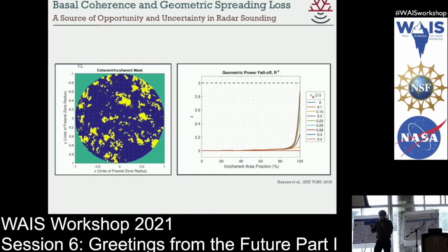But the difference is if you have a radar signal and it comes out, it spreads out like a sphere, right? That goes like 1 over r squared. And if the reflection on the bottom is like a mirror, then it keeps going. That's 1 over r squared the whole way. If you go out and you get 1 over r squared coming down, and it's rough and it scatters, on the way back, it goes like 1 over r to the 4th, right? This is giant when you're talking about what is the difference between airplanes, which we fly, and orbit, whether your distance r goes like, losses go like r squared to r to the 4th, totally different scenario.